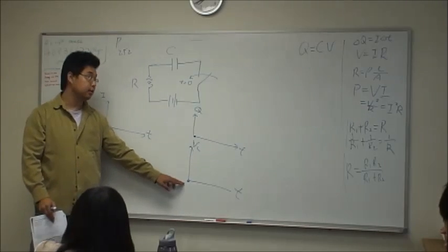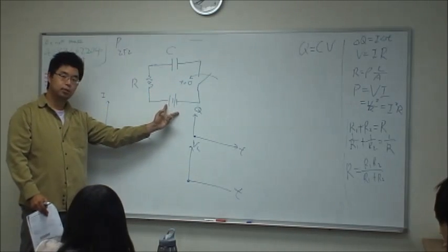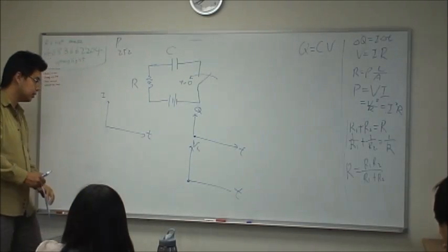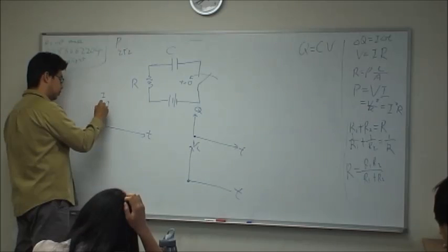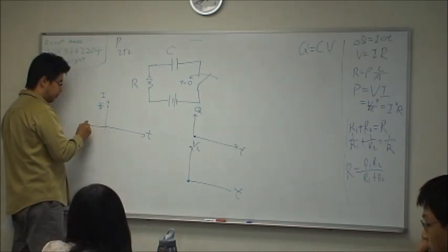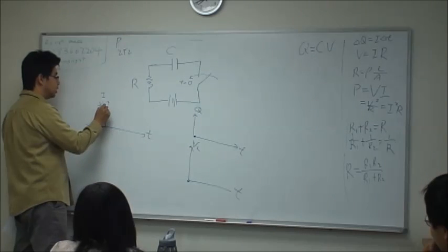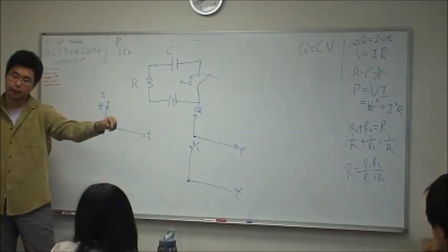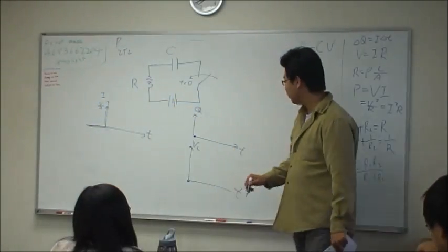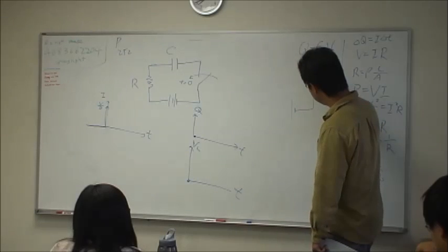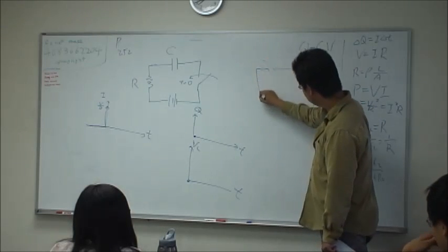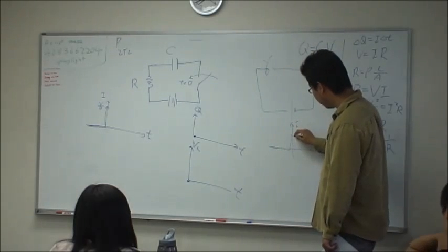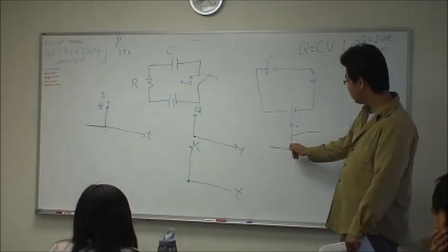If the voltage is 0 across this part, there's a certain voltage here, right? So what's the current here? V over R. Make sense? V over R. So at negative time, it's all 0, and suddenly it will jump to V over R in terms of current, as soon as you close the switch. Okay? This is a similar thing. If I just have a battery with a resistance and then a switch, okay? When I close it, immediately you will find that the current will jump up. Make sense? As soon as I close the switch.